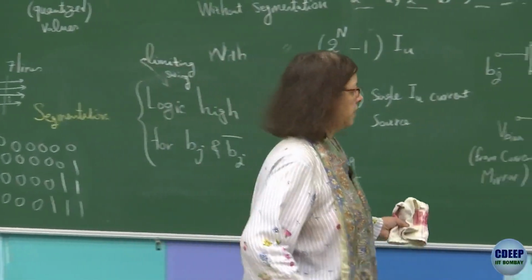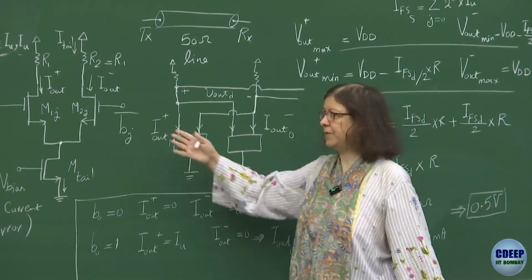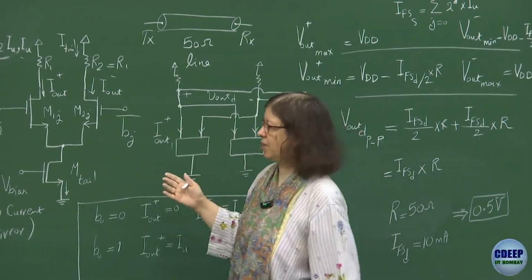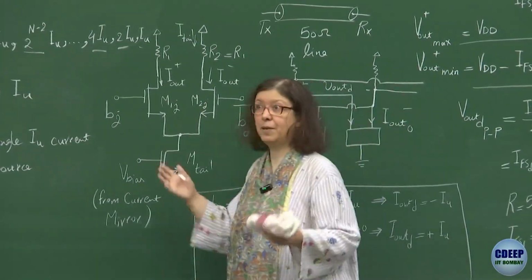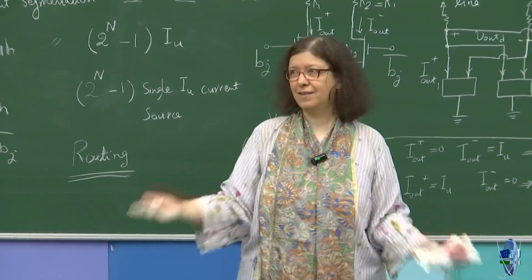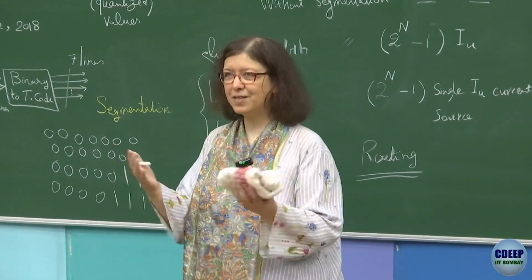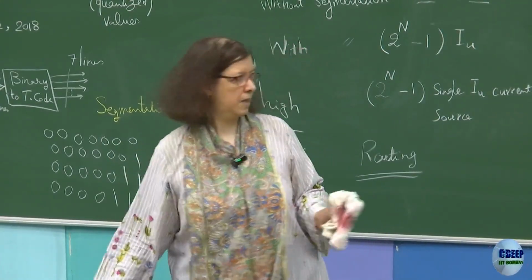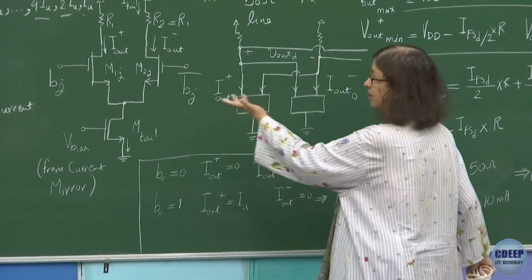Those sharp transitions, unless they are a very small fraction of the frequency, are a big deal. So that's why you cannot transmit, because one of the questions always is this: okay, can we just remove this physical, in fact, metallic channel and use air? Why can we not connect cores, say multi-core computational cores, using wireless links? Because bandwidth is too high. Wireless communication is based on a limited bandwidth, very narrow compared to carrier frequency. That's why other channels, like optical channels, are used.